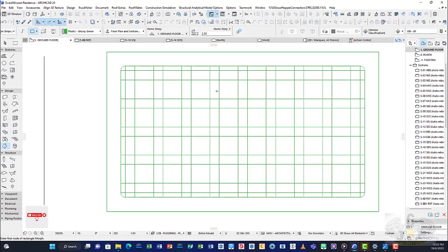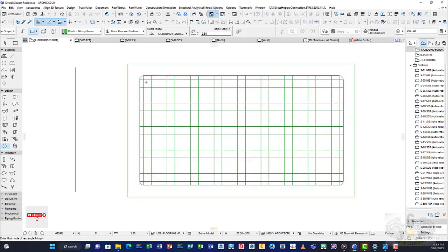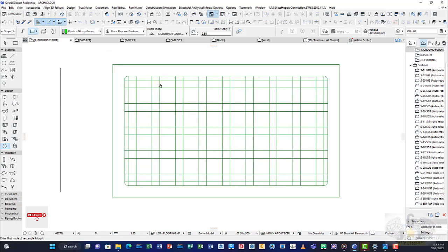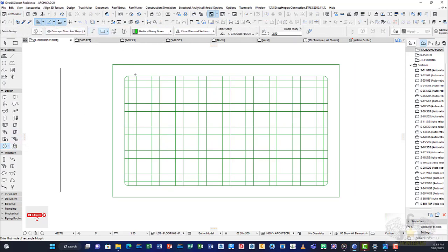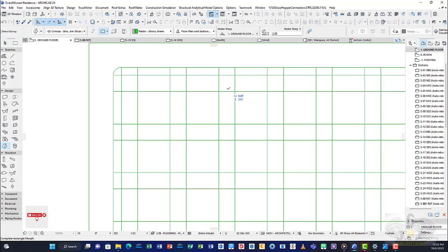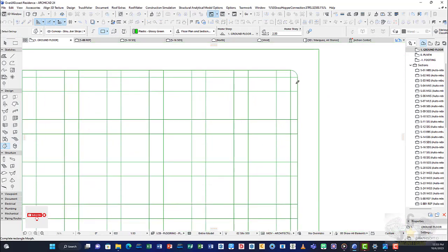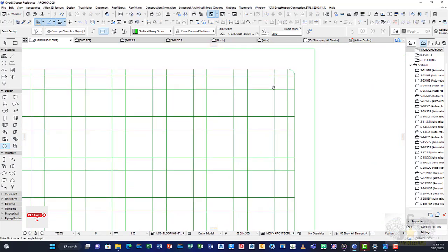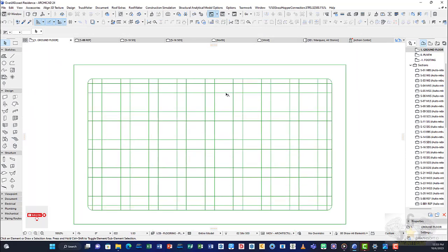So what's going to happen here? I start creating profiles, right? I told you that there are two ways while using the morph tool. The first way is to use these geometries. So I come like this, I click here, I go all the way to this corner, then I click again here. If I press escape twice, I get out. When I come closer to it, pressing down the space bar once, before clicking, you see that there's a preview.